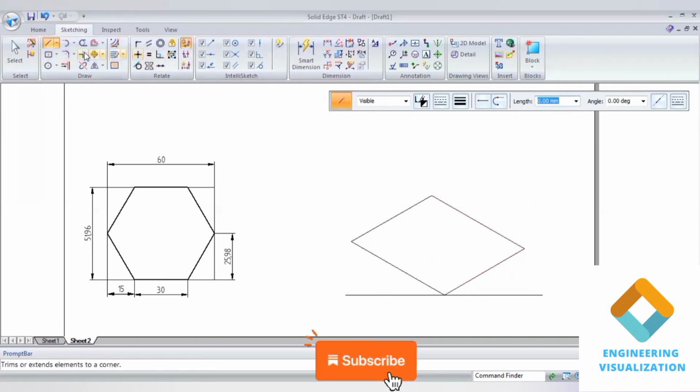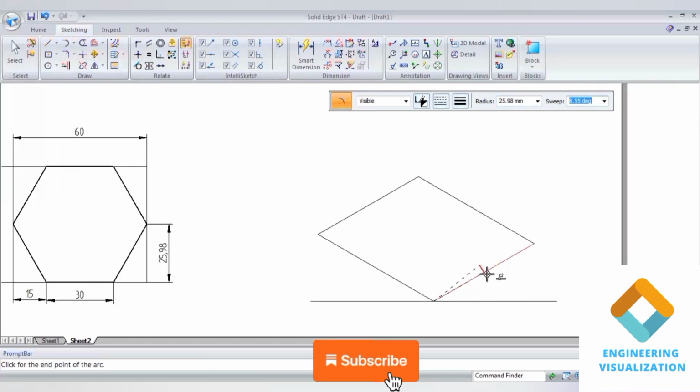Now we have to cut the arcs. For a length of 51.96 we will be cutting an arc of 25.98. Take the radius and cut the arc. The same way on the opposite side, I will be cutting the same arc length, 25.98.